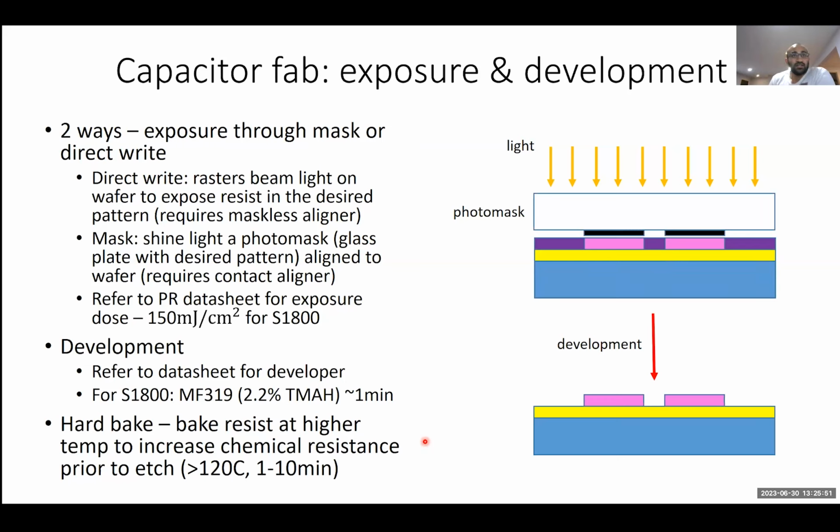So in our process, as mentioned earlier, we use the S1800 series, and from the data sheet, I can look up the exposure parameters and the developer compatibility. So our process ends up using a TMAH developer, MF319, and we develop for around 1 minute, and that's enough to remove the regions of resist that have been exposed